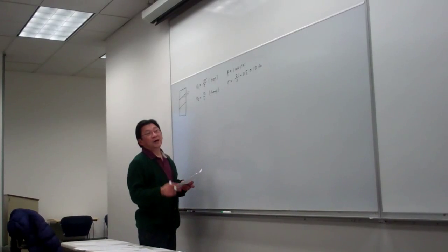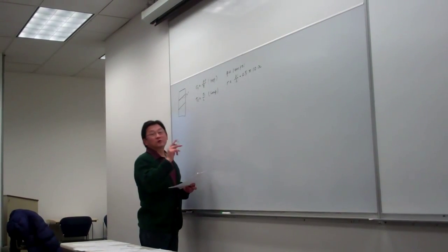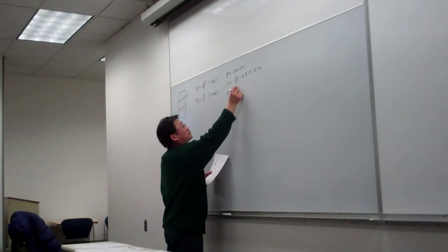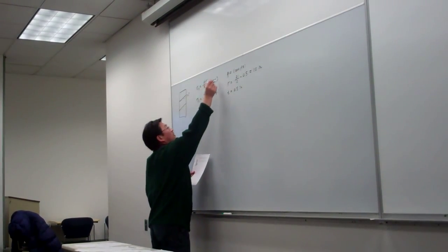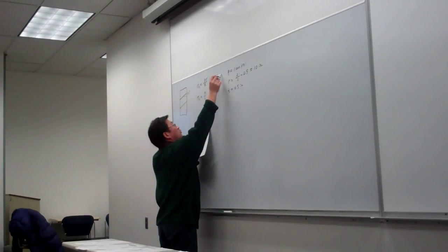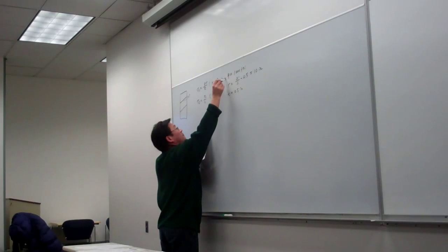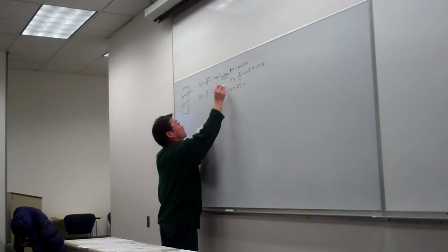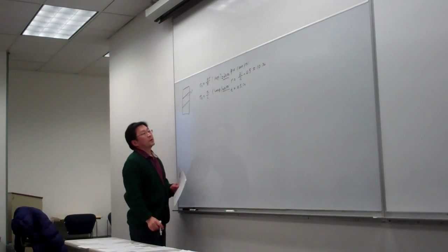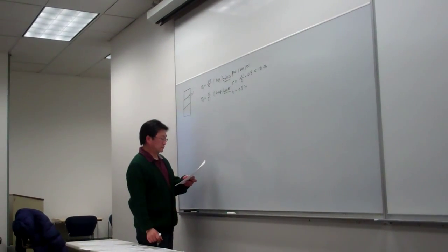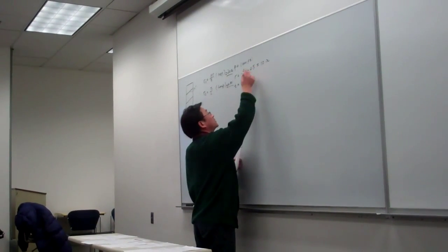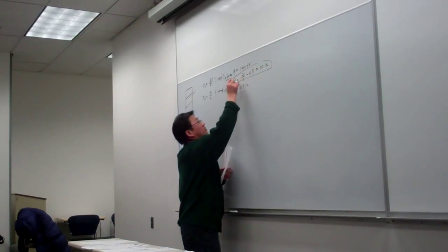Okay. So here I emphasized in class the R should be the inner radius, and T is the 0.5 inch. So plug in here, then you should be able to calculate sigma 1 should be 20 ksi. This one is 10 ksi. Okay. So here I really want to emphasize, if you have the mistake here, I take the 5 points off.